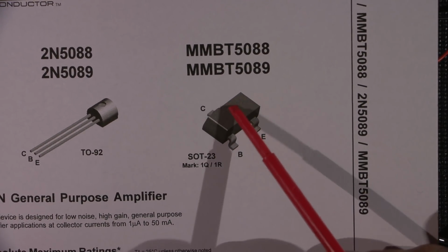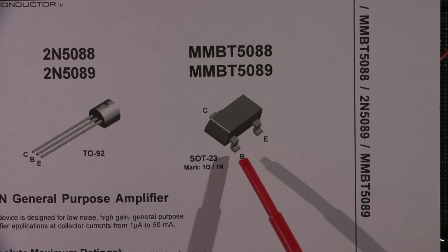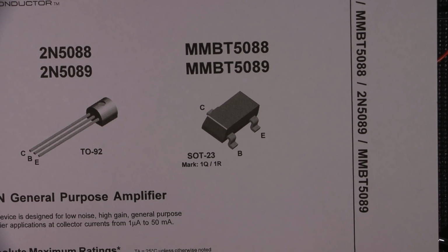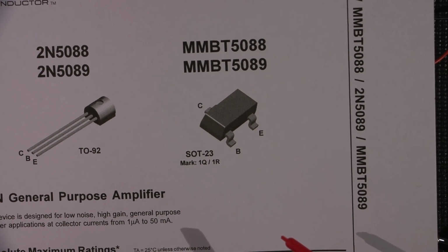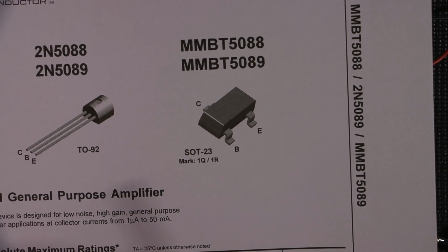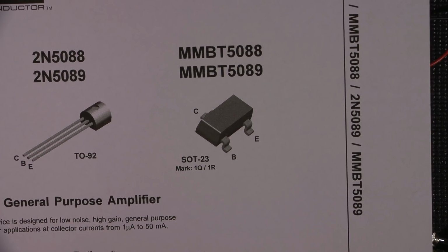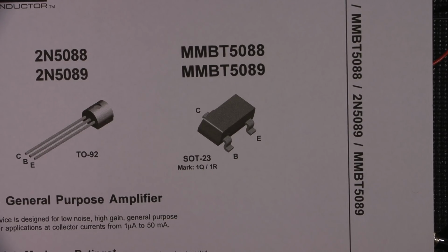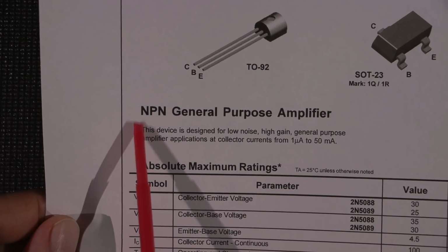So this is that transistor right here, SOT23, and as you can see, it very comfortably labels base, emitter, and collector. Now this is the same for PNP transistors as well, and we wouldn't know at this point, if we're very quickly looking at this, what we've got going on here. So one way to very easily verify this is just to use a standard diode checker on your DMM. So you can see why I used this in this application.